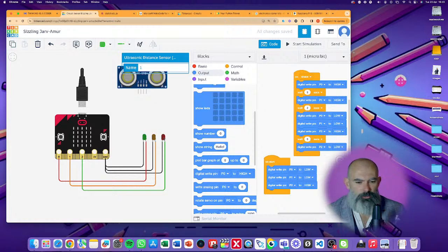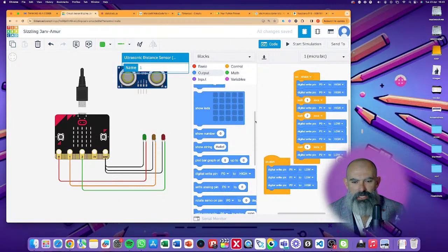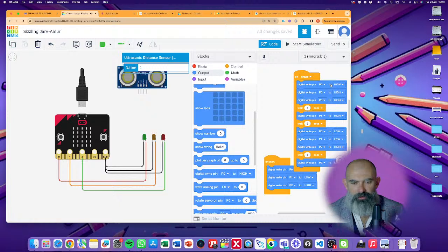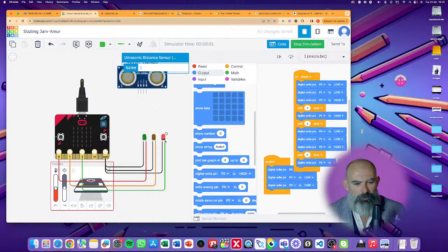So this is when we test. While this worked for our loop, we need to go in and actually, on shake, we need to make sure all the other lights, no matter what else is happening in our life here, are switched off. Low, low, low. So pin 2, pin 1, and it's just the green light, which now changes. So we press start. We've got the red light forever. We click the shake, and now it goes through the 5 second wait, the 2 second wait. There we go. Works. And this is the kind of thing that happens.